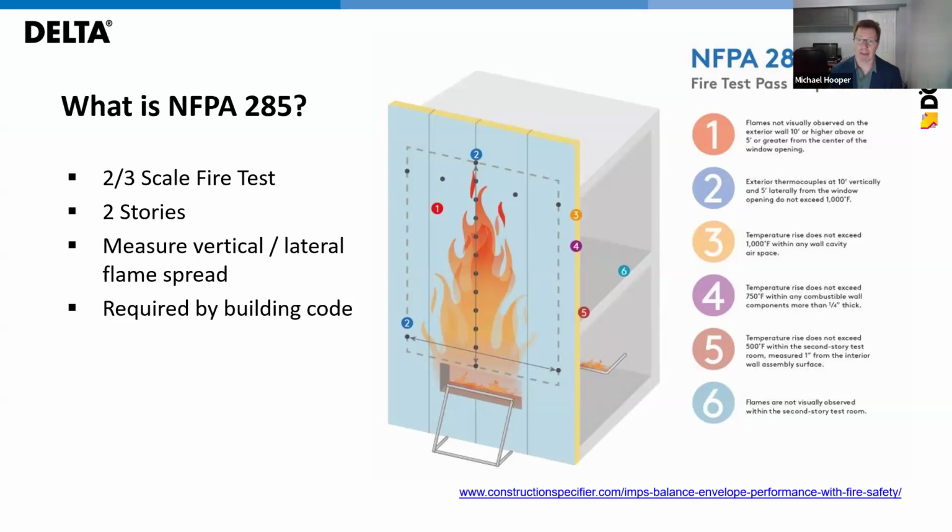In order to pass this test, there's several criteria that need to be met. First and foremost, the flames cannot extend beyond 10 feet above the opening in a window. The thermocouples at 10 feet cannot exceed 1,000 degrees Fahrenheit.